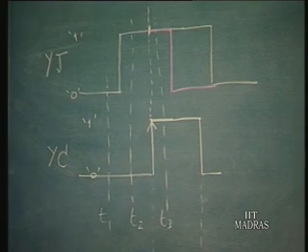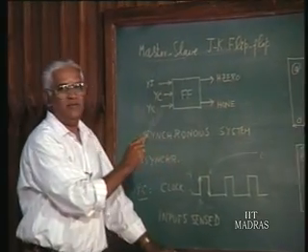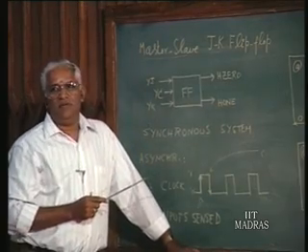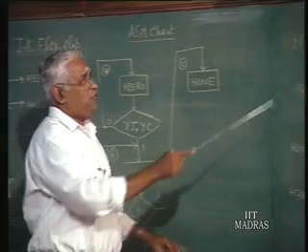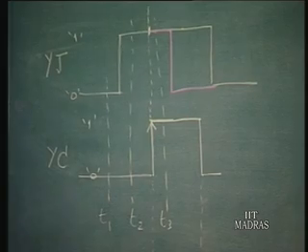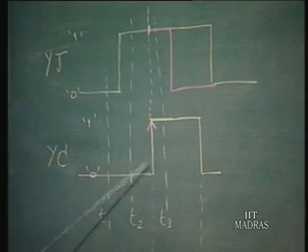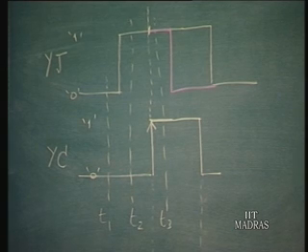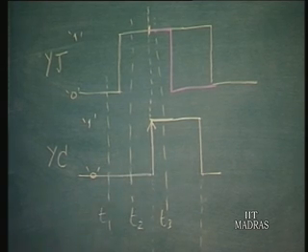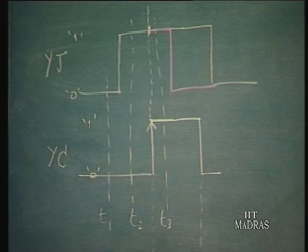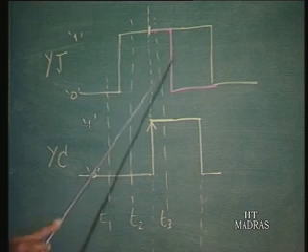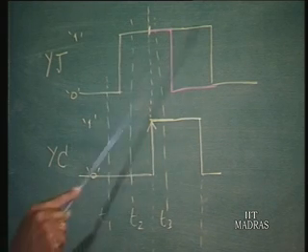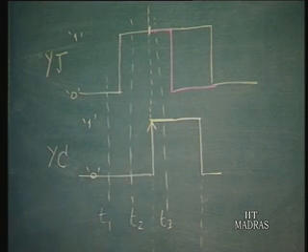That in fact is the principle of the master slave component. So, the inputs are sensed at a particular instant and outputs are generated at a different instant. But of course, the instants are related by the clock, it is not arbitrarily different. So, whether J had changed as shown here or as shown here, it does not affect the output.